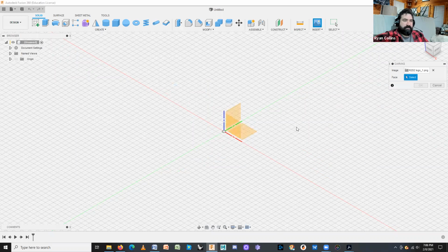You will have to select what plane you're working on. Like I talked about before, the x-axis, which is your red, goes left, right. Your y-axis, the green, goes front, back. Z-axis, the blue, goes straight up and down. You can work up on the wall, which would be the XZ axis. You can work flat down, which would be the XY axis. You could work at a diagonal, or not a diagonal, at a perpendicular. I would default to the flat plane, the XZ axis.